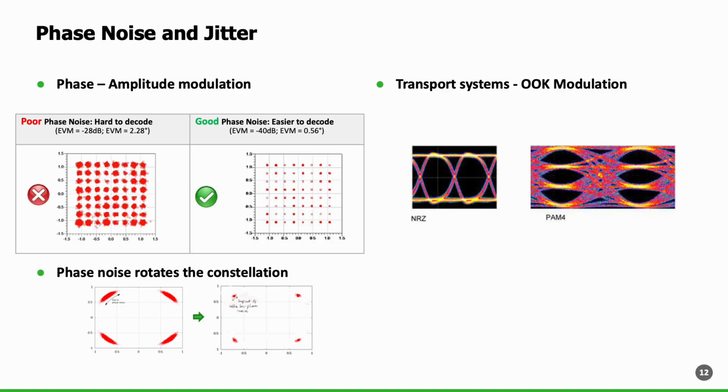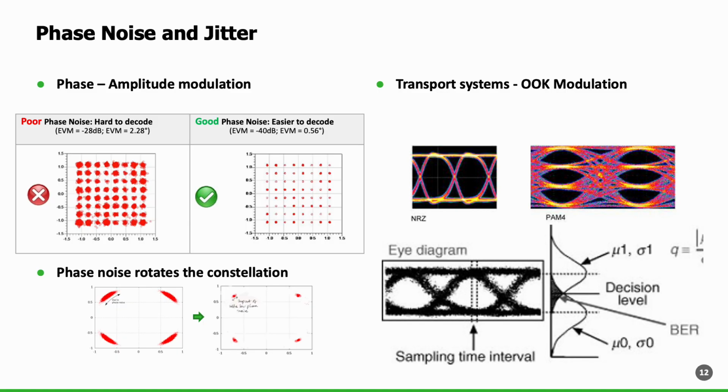Wired systems traditionally used amplitude level based decision methods, and thus clean eye diagrams are important for better decision margins and low bit errors. Clocks with less jitter drive eye diagrams with good height and width. Systems perform jitter or phase noise cleaning on the network recovered clocks to make them suitable for the end application.